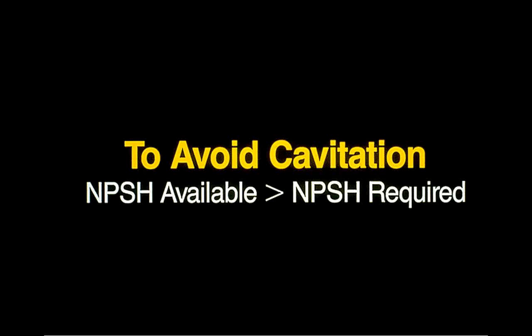We had a question that just came up, does NPSHR depend on fluid type and temperature? It absolutely does. Hot water, let's say you're running hot water at 150 degrees F, you're going to have a different specific gravity, and then that brings into play your vapor pressure at the eye of the impeller.